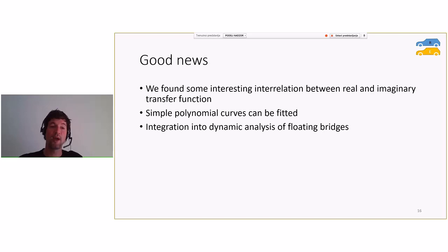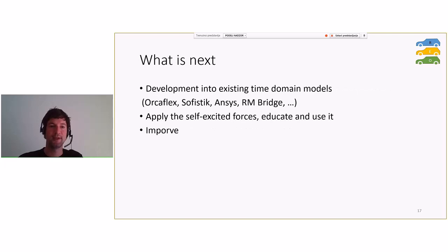And this is now, of course, an integrated part of our dynamic analysis of floating bridges. We are now able, in a very simplified way, to simulate these flutter derivatives. We have developed the method that introduced those equations into dynamic equations, and we have also simplified a polynomial approach, which has been approved and published.